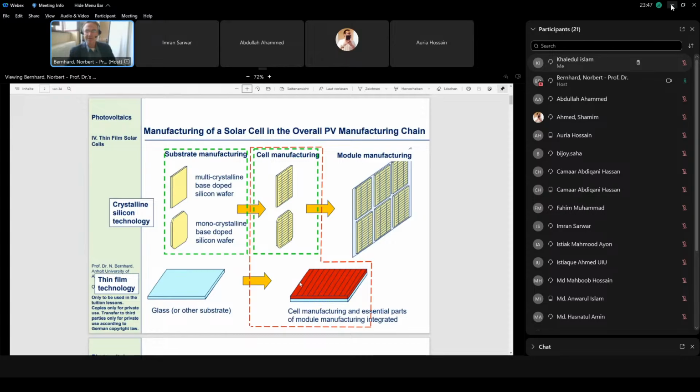And first, what we see, we always have a semiconductor here in light yellow, and a metal in gray. And the TCO stands for transparent conducting oxide. That means TCOs are materials which are transparent as glass, but which are conductive, usually with a higher conductivity than a semiconductor, but less than a metal.